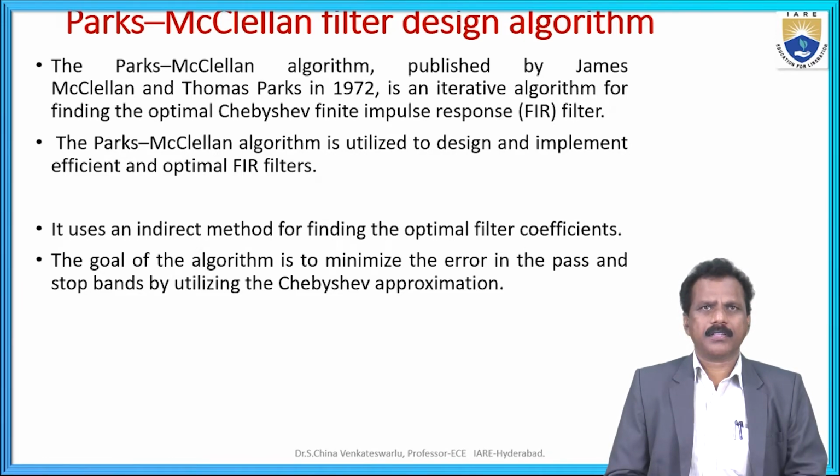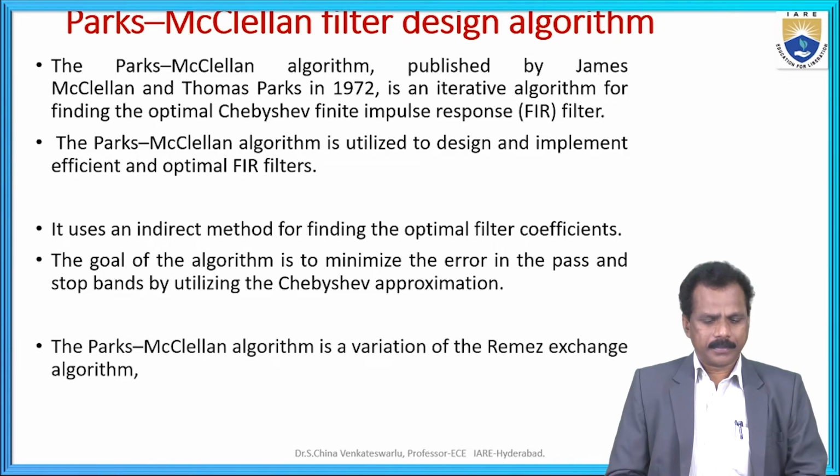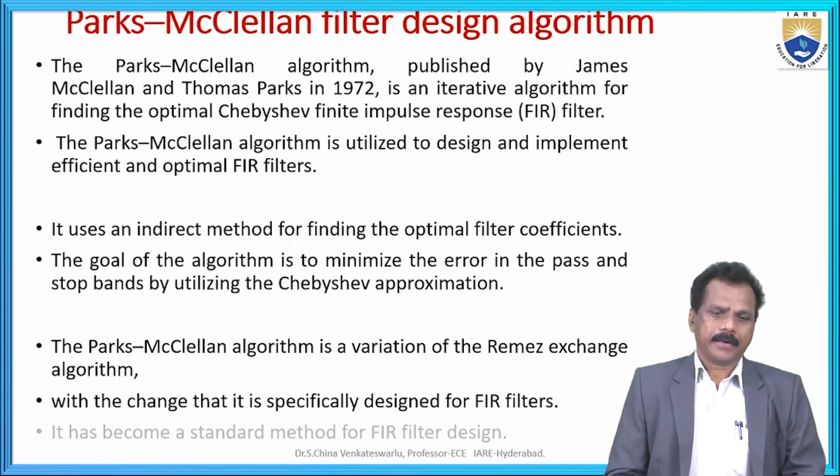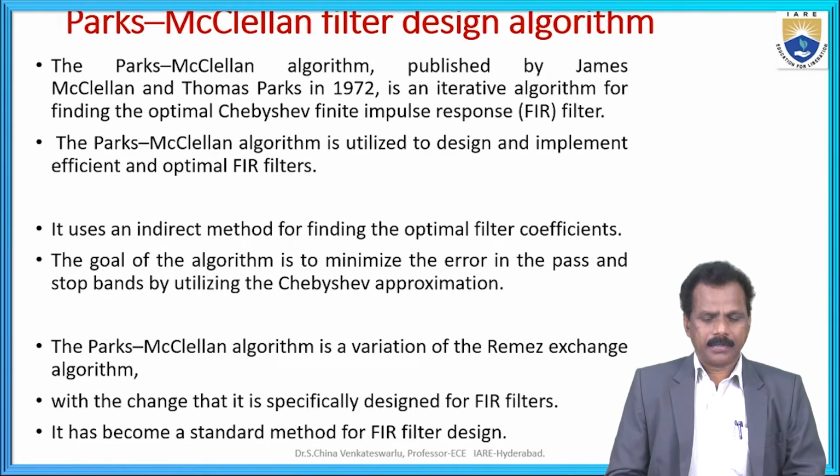That's the main significance of choosing this optimum filter. The Parks-McClellan algorithm is a variation of the Remez exchange algorithm, with the change that it is specifically designed for finite impulse response or non-recursive filters. So it has become a standard method for non-recursive filter design like finite impulse response digital filters. That is the significance and importance of the Parks-McClellan filter design algorithm.